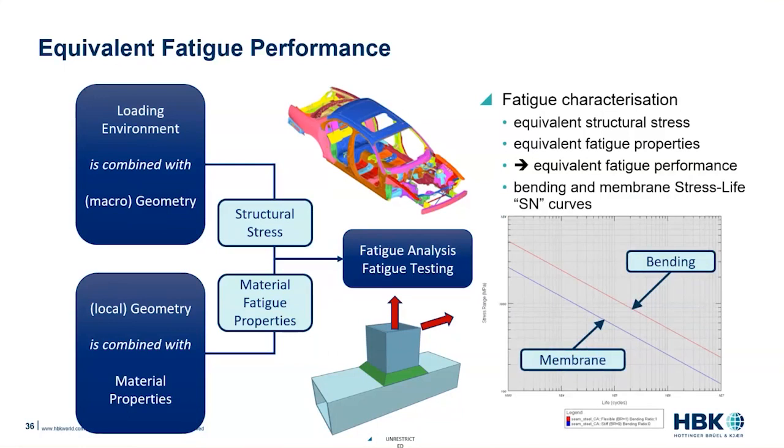By having two curves like this, one for bending and one for membrane, we can interpolate between them for any given ratio of bending stress to membrane stress. Okay.